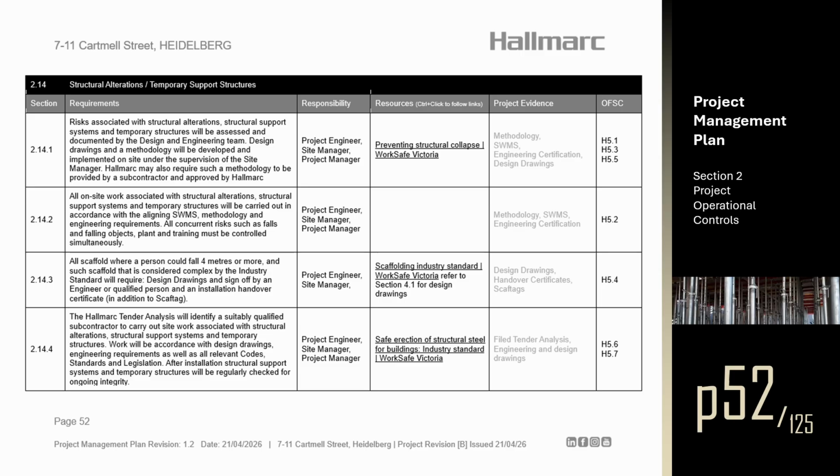Section 2.14.3. All scaffold where a person could fall 4 meters or more, and such scaffold that is considered complex by the industry standard will require design drawings and sign-off by an engineer or qualified person, and an installation handover certificate in addition to a SCAF tag.